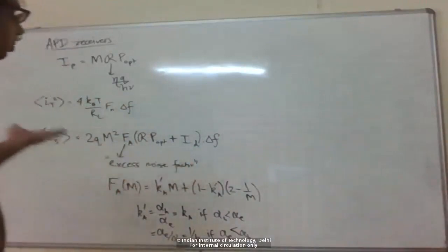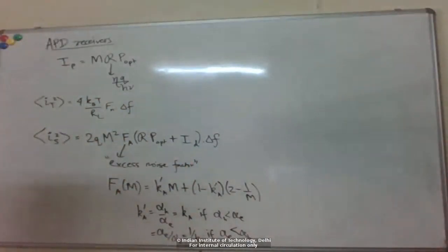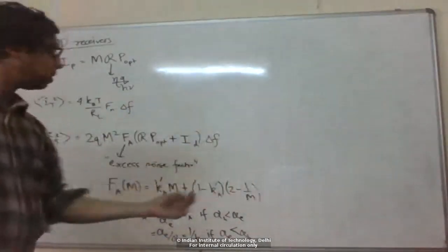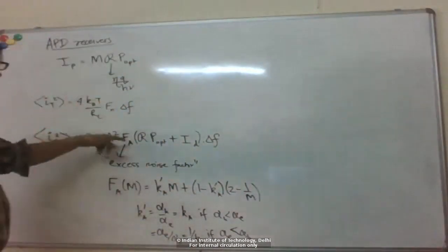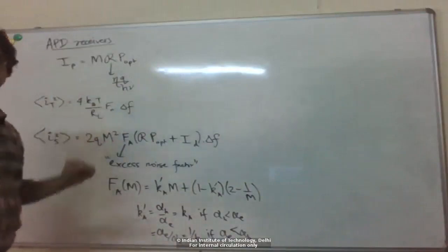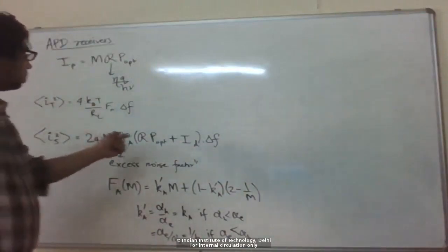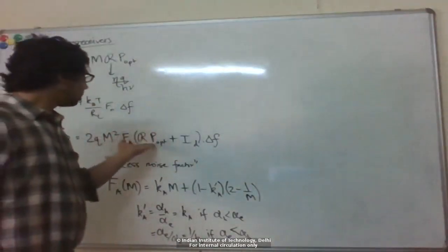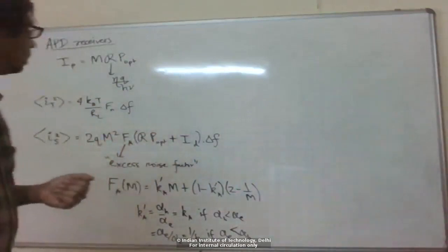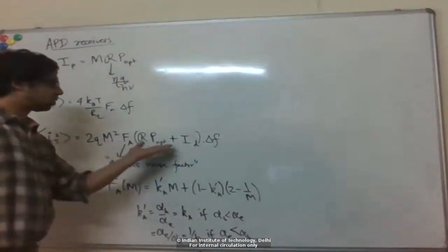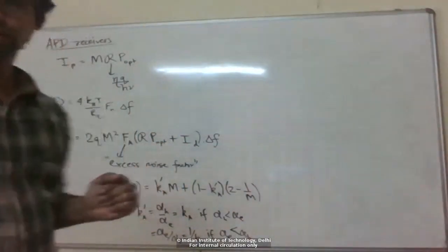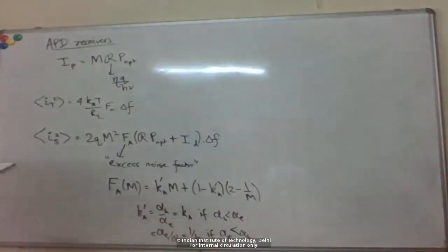For the pin photodiode to get into the shot noise limit, our optical power had to exceed a certain value such that it became larger than the thermal noise. So we are at large optical powers where the dark current is low, but for APDs, we might already be in the shot noise limit at low powers where dark current may not be negligible.